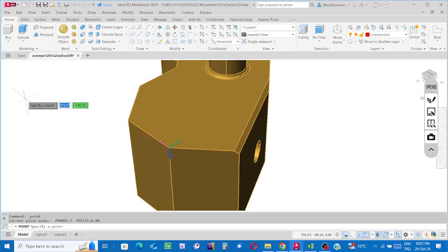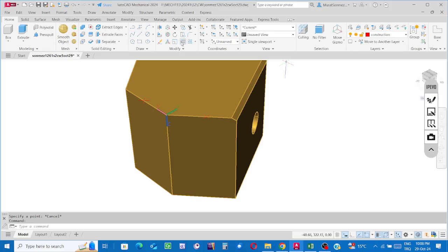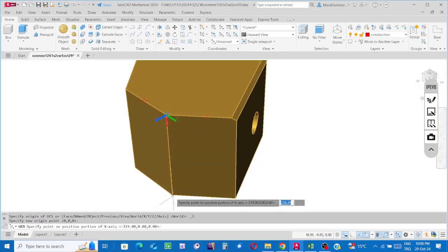Yes, distinguish the second point, and then press escape button, and then coincide the x-axis. Click on the displacement button. Well, I'm going to coincide the x-axis along this edge, so while this surface is being highlighted or that surface is being highlighted, indicate this point as the origin and indicate this characteristic point as the second point along the x-axis.